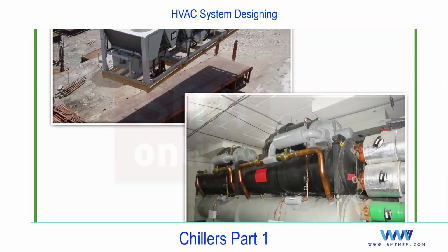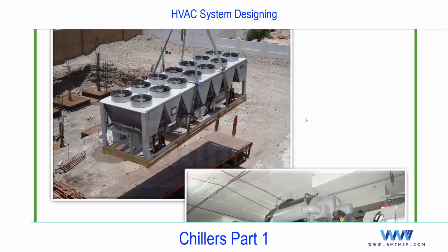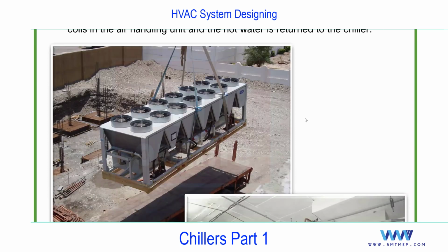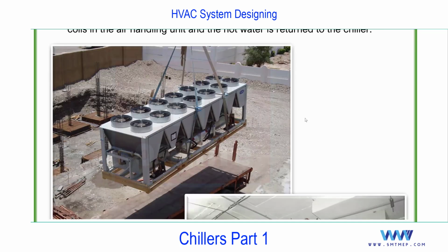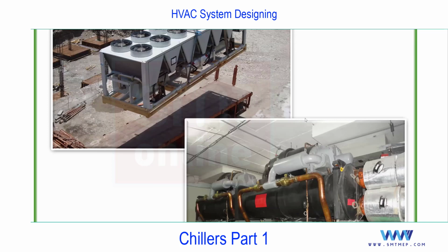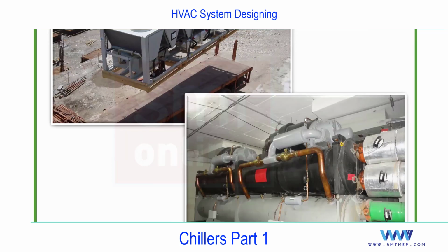So remember, this can be an interview question. First question can be what is chillers? And the second question is the types of chiller. If they do not add the type of chiller according to the compressor, in that case, they are asking about the type of chiller related to the condensing side only. So there are two types of chiller. If you talk about the condensing side, one is an air-cooled chiller and second is a water-cooled chiller, commonly used in actual practice compared with the other types. Okay. So what exactly is the difference between these two chillers? You'll get the idea after learning the cycle of both the systems.